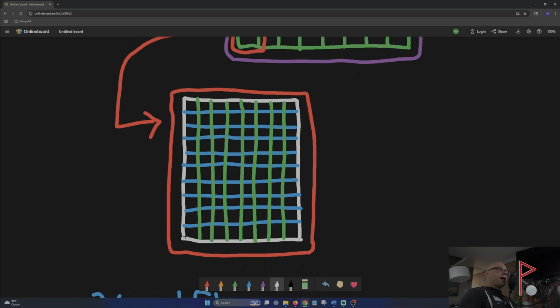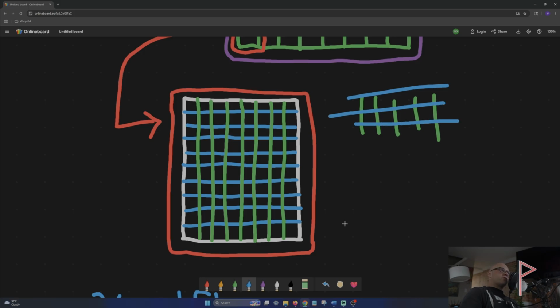So if you were to expand here from these bit lines in this crude drawing, for example, here's your bit lines. And you know, you got your rows going across, and there's your rows. And then, of course, as we explained when we were talking about tREFI, these bit lines kind of terminate at your sense amplifier. And again, the tREFI example, why I chose that first is because you can explain all of these things so simply by understanding tREFI. We know what the sense amplifier does.